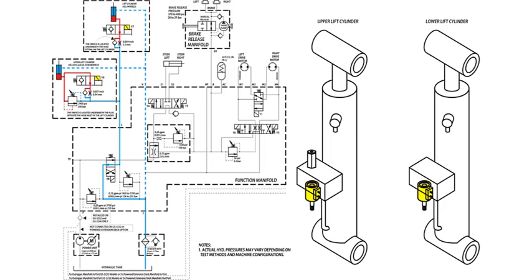Y7 and Y9 are the solenoids used to activate the lowering valves located on the lift cylinder, or lift cylinders, under normal machine operation. In the de-energized, or spring return position, these valves are used as holding valves. When the down function is selected, the lowering valves open fully, allowing the oil to exhaust from the barrel end of the cylinders. Exhausted oil is metered out of the lift cylinder, as it is forced through a fixed orifice. The orifice size varies between different size machines. Once the oil passes the fixed orifice, it is allowed to pass back to the reservoir through the spring return position of the lift drive select valve.